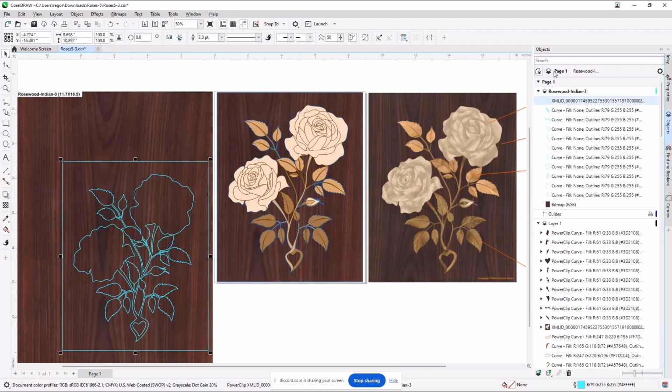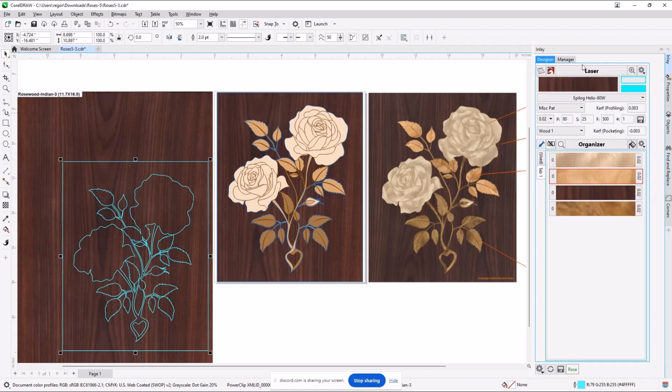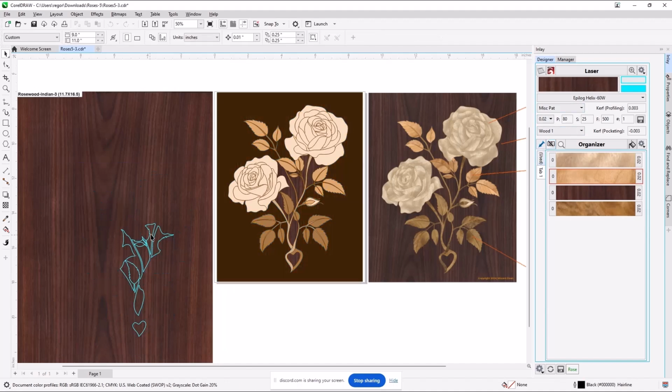That means basically going back to your inlay. If you make a change on something over here and it's still attached to the veneer, this picture doesn't change. It's not connected that way. So you have to remember to select what you're going to get rid of. I'm going to remove that portion of the design and I'm going to remove it from the veneer. And notice it's stepping through quietly and doing these pieces one at a time.